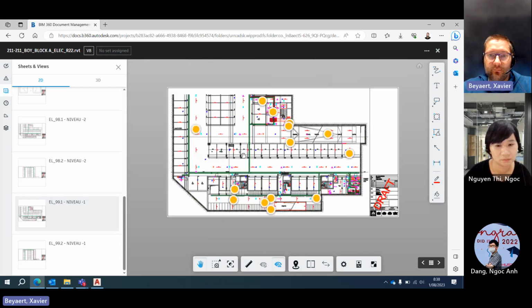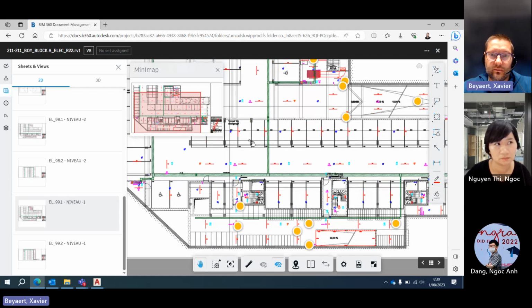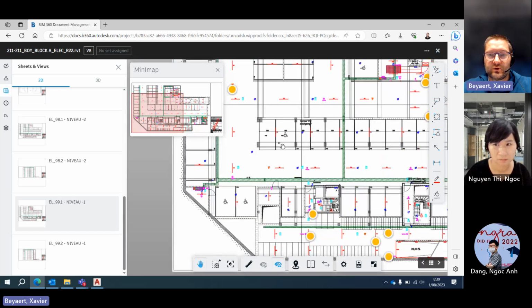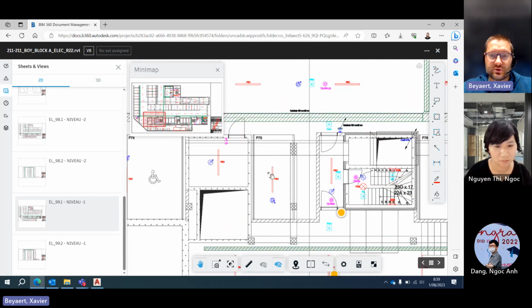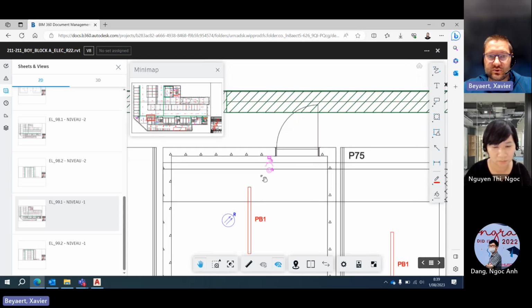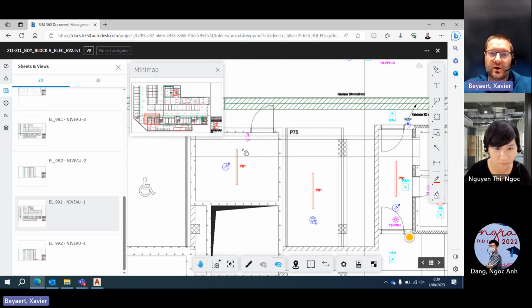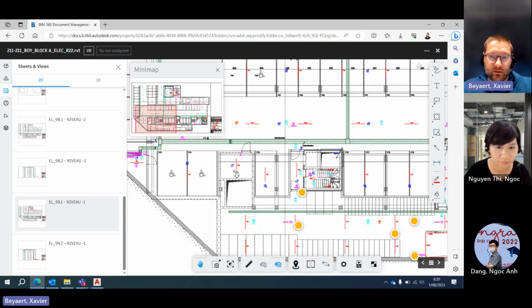And for the rest, it's lighting for the parking area and the bike storage here. It's a DALI system. So what you have is just a feeding line for the technical rooms and so on. We have push buttons, so we need interrupters, switching relays to control that lighting.